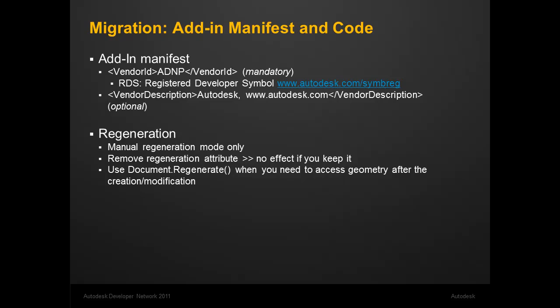Thankfully, the changes for Revit 2011 to Revit 2012 are quite minor. Now, in order to make the existing code in Revit 2011 DevTVs to run with Revit 2012, we will need to make the following minimal changes. The first change is the Addin manifest file. We need to add a vendor ID tag in the manifest file. This is a compulsory step.